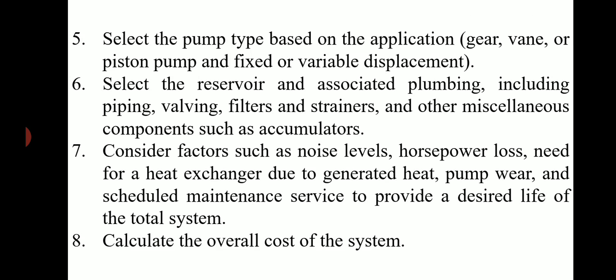Fifth one, select the pump type based on the application: gear, vane or piston pump, and fixed or variable displacement. Sixth one, select the reservoir and associated plumbing including piping, valving, filters and strainers, and other miscellaneous components such as accumulators. Seventh one, consider factors such as noise levels, horsepower loss, need for a heat exchanger due to generated heat, pump wear and scheduled maintenance service to provide a desired life of the total system.